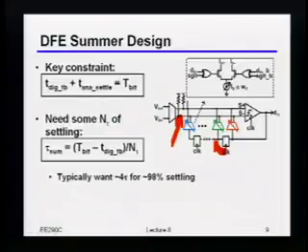For those signals with relatively small voltage margins, you could make an error, right? So you are right that if the nonlinear impedance of that node is sufficiently low compared to your load resistance that you basically don't get the amplitude you want, then that indeed would be a problem. But that's a much easier problem than actually making this a truly linear summation. It's not necessary to make it linear. Exactly. No, that's absolutely right.